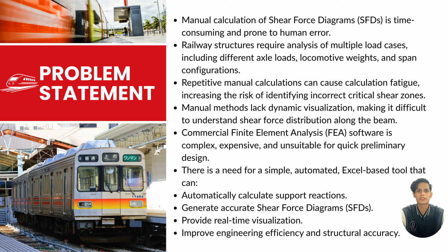Engineers need to analyze the different axle loads, locomotive weight and load position according to railway design standard. As a result, the same calculation must be repeated many times. This repetitive process can lead to calculation fatigue, which increases the risk of mistakes and may result in incorrect identification of critical shear force zone affecting structure safety.